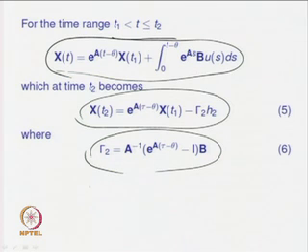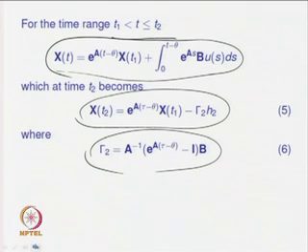Now, x is the state variable and we will get the values of the state variables. So, we shall have two values for the state variable at any instant of time. Therefore, x(t2) will also give us two values. So, one has to keep in mind that the states we obtain are not scalar values, rather for a second order system we will obtain two elements for each state vector at any instant of time.